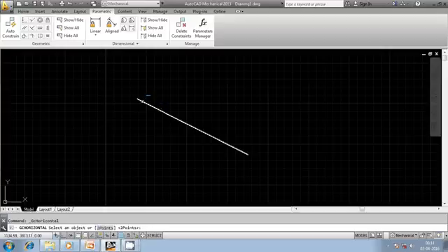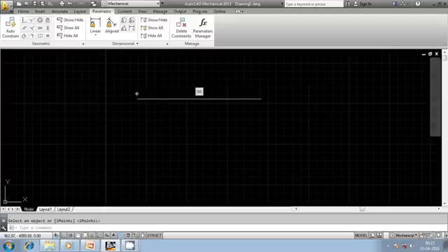If I click on this entity nearby to this point, this point remains constant, whereas the other point will orient with reference to the first point. Let us select. I am selecting nearby to the first point. You can see here the first point remains as it is, and the second point got oriented with reference to the first point. You can also see here there is a symbol, that is the geometrical constraint. Now the geometrical constraint is applied to this geometrical entity. That says that it is horizontal. Right now it is horizontal. You cannot incline the line.